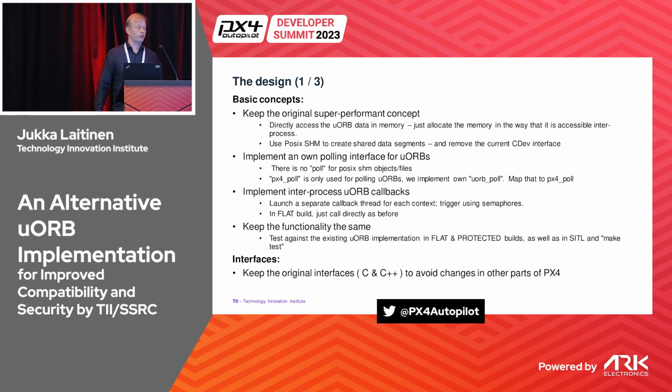And we wanted to keep the functionality the same, so we tested the new uORB implementation against the existing one running on STMs, on the Linux simulator, and of course with the test framework that is in PX4. And as I said earlier, we kept the original interfaces to avoid any changes to other parts of the PX4.